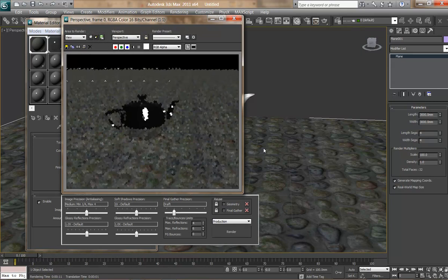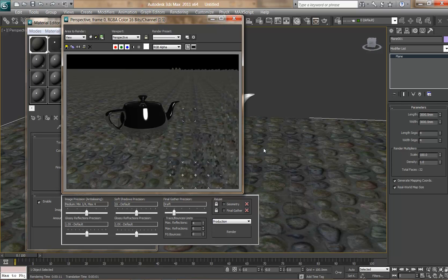But still, it's only going to be marginally better when I render, because I've got materials on my objects, but I don't have any lights in the scene. Lights are critical. Now, in Revit, and a lot of other CAD programs, you can make lights. And they're actually mental ray lights. But I'd recommend you don't worry too much about the lights, for rendering at least, in the CAD programs.